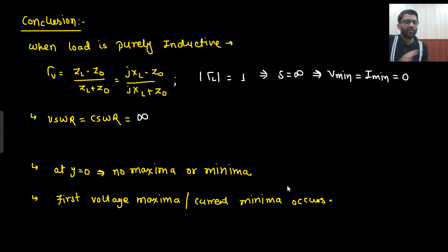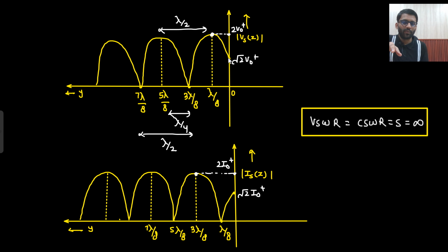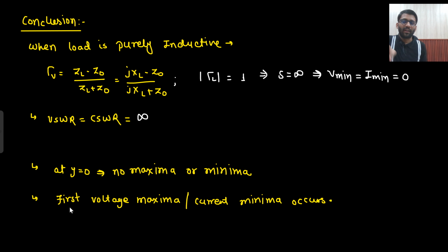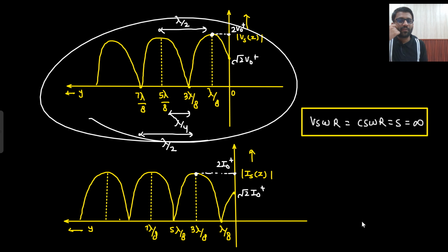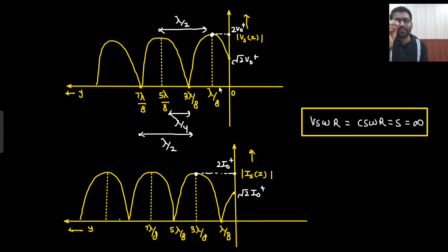At y equals 0, there will be no maxima, no minima, you cannot conclude; there will be some value. And first voltage maxima or current minima will occur. So if this kind of standing wave pattern is given, you will get to know that certainly the load is inductive. Say yes or no.